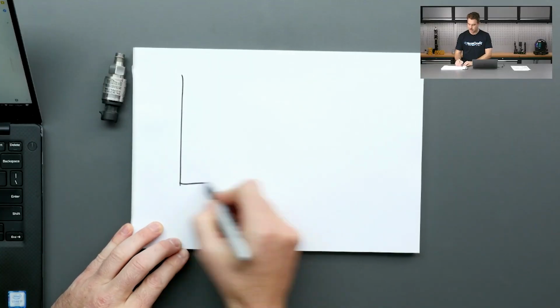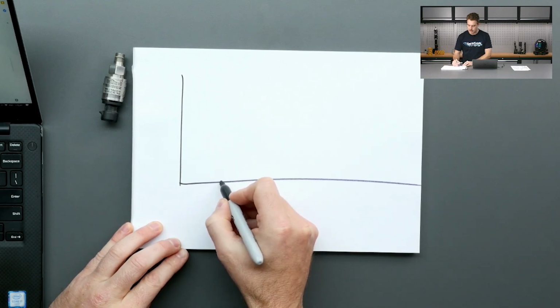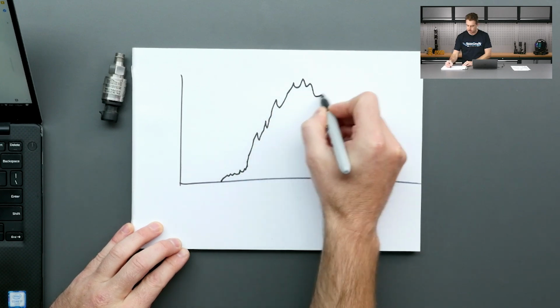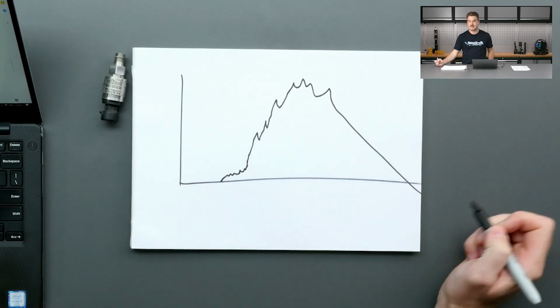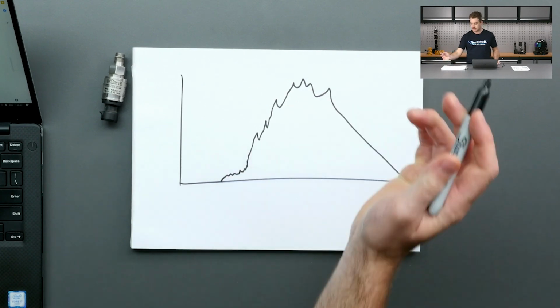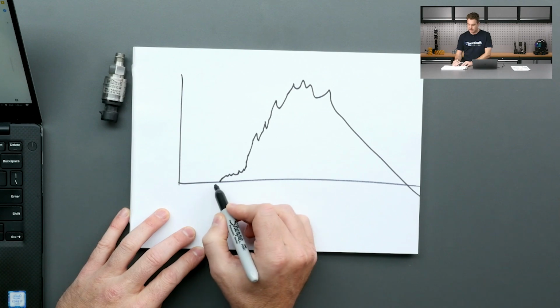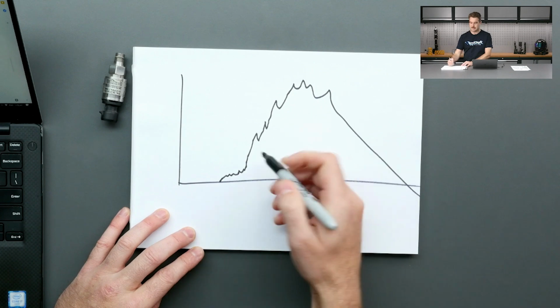You also asked a question about smoothness, and it's got some similar stuff in there. So brake pressure smoothness, what that means is if we look at the same similar plot to before, but let's say our real brake signal looks like this. We want to quantify basically how unsteady that signal is, particularly on release, but it doesn't matter. For application, it's the same concept. So what we want to do here is come up with a number for how spiky or how unsteady the signal is.